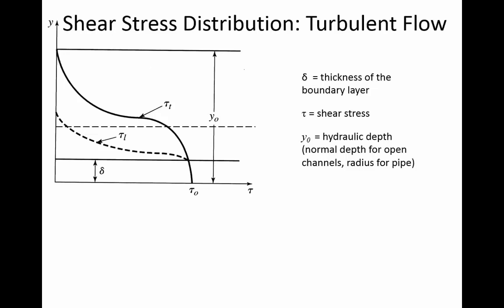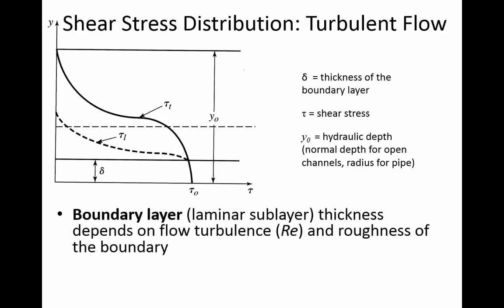So can you distill all that down into 2 or 3 sentences for a quiz? I don't know. The boundary layer is that section shown here. No matter how fast the water inside the center of the pipe is going, there is a section around the edge of the pipe that is laminar. Remember that right at the side of the pipe, the velocity of the flow is 0.